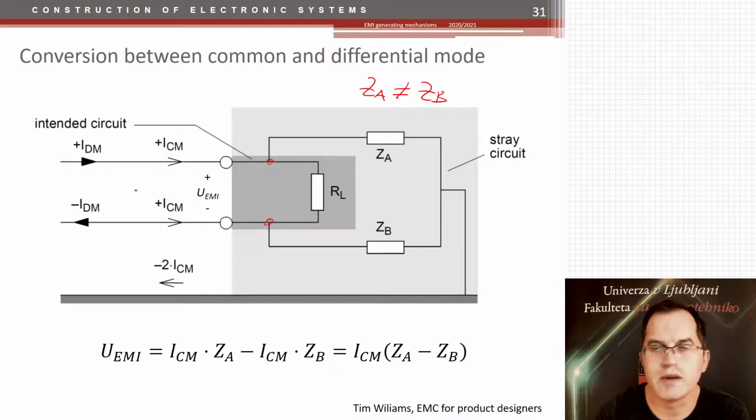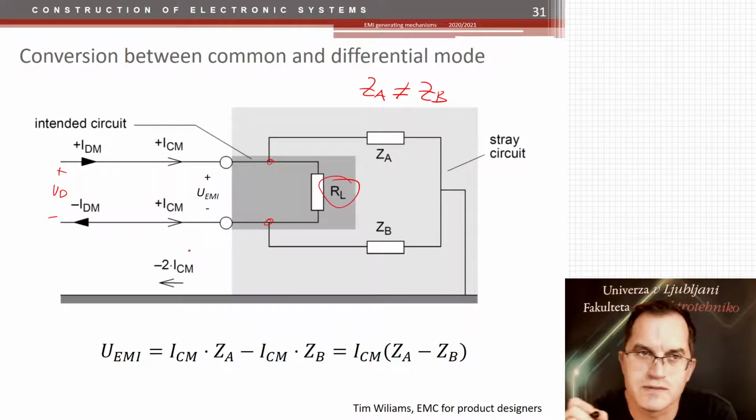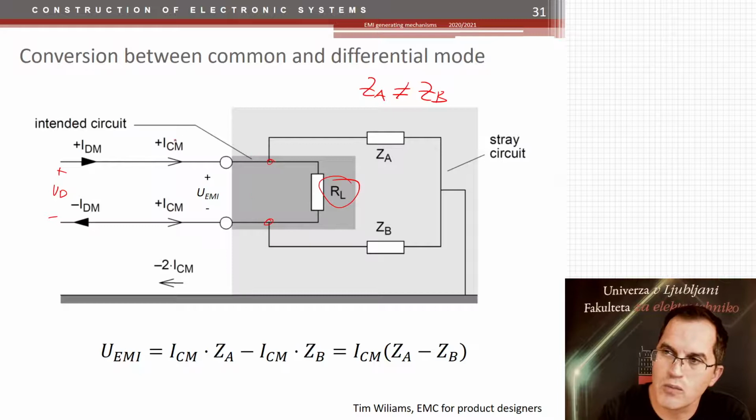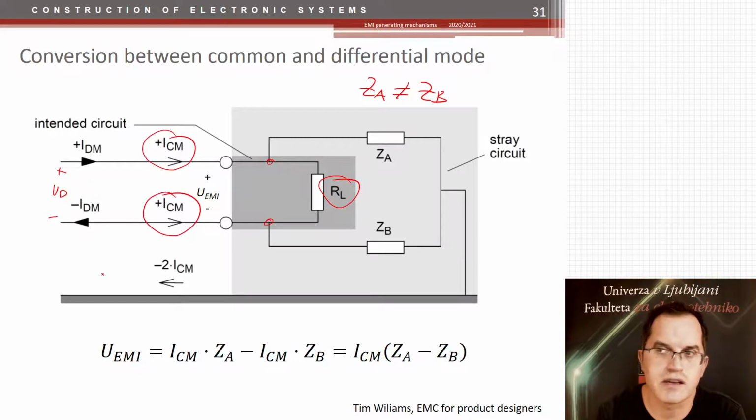Usually your information is transferred from one part to another using differential voltage. Now this differential voltage is then transferred to inside of the receiver, which is represented by this load resistance, and the information is safe. But if you have a common mode noise that is coupled to these two lines in the same direction, if there were these two stray impedances, it would not affect it.